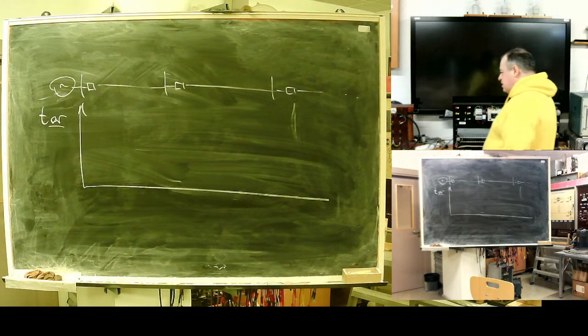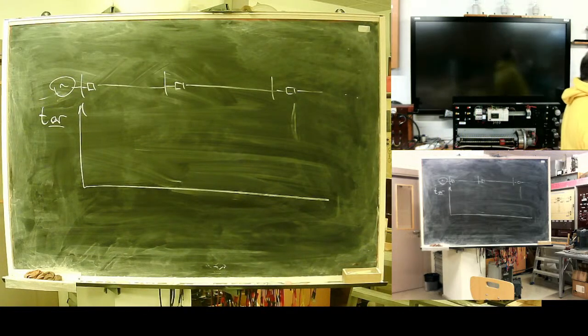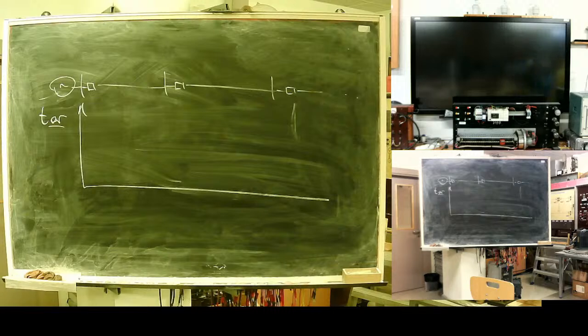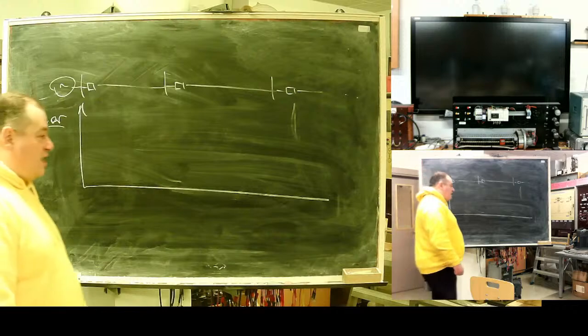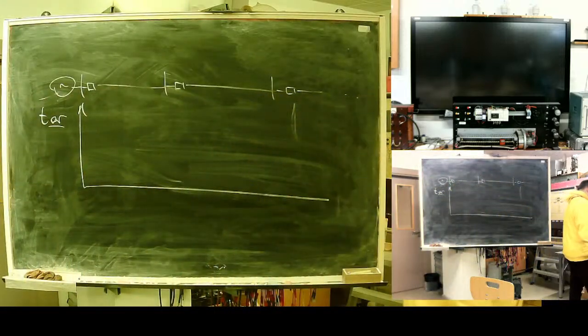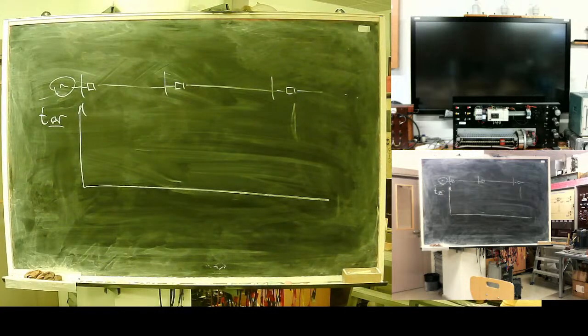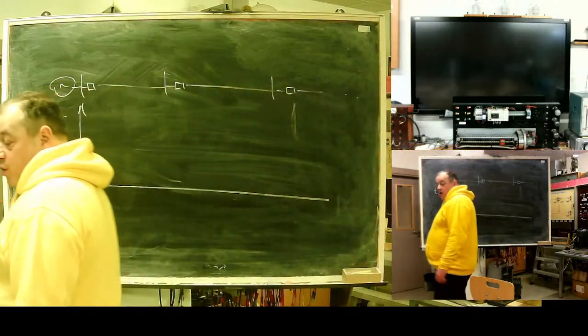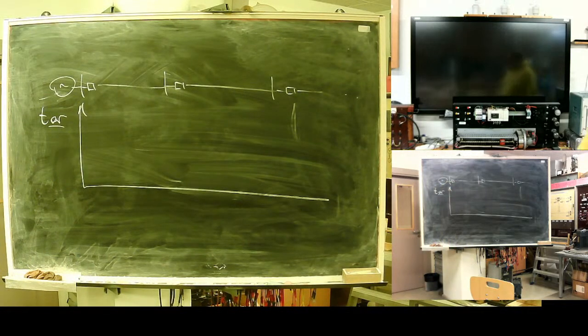One thing. Another, many network operators adopt a policy of safety, not creating a backup channel for the case of current protection fault. One of the driving factors, if we have so-called reclosers, I have one in 4.4. A recloser is a device that can be put on a pole. It's a circuit breaker with a simple overcurrent relay for classical reclosers. Modern ones are equipped with quite sophisticated relays, all kinds of protection, a basic set of protection at your disposal, and